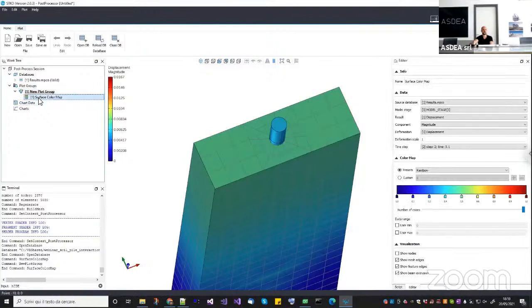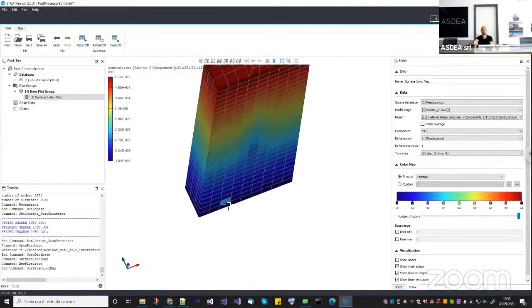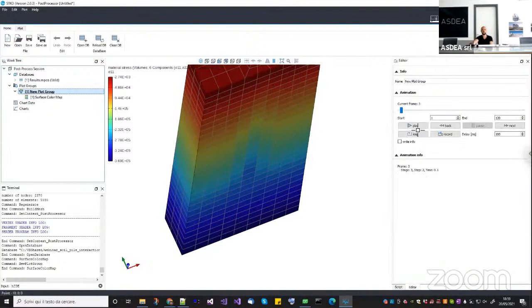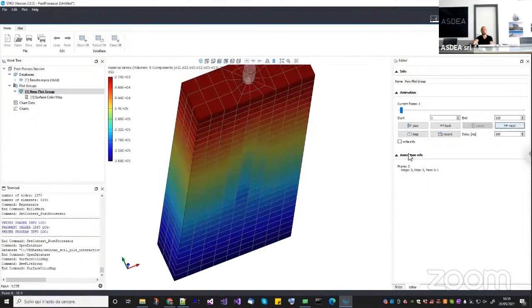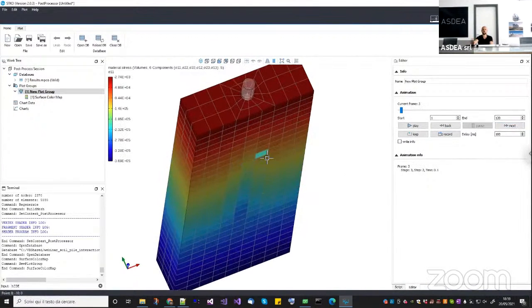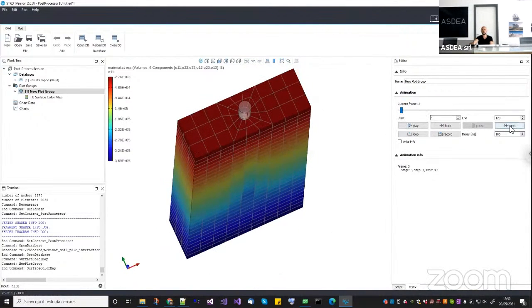But actually, if you look at the stresses, they are still there. If I visualize the material stress, as you can see, you still have stresses due to vertical weight, okay? Let me go back. As you can see, I have the stress state here, and I still have the same stress state here. So this is the importance of using initial state analysis. You can reset the displacement while keeping the stresses. And then if I go on, now I have 10 steps of vertical displacement. So you can see 0.4, 0.5, the beam is going down, and then horizontal analysis, okay?